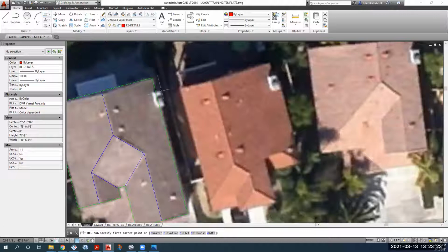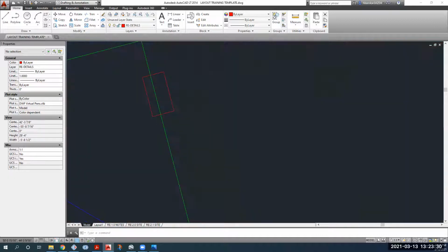To do that, I took this rectangle tool again. I made this approximate tracing of where that chimney is. And basically what I'm going to do is first trim this line. As you can see, this line segment and this box meet at these 2 points.